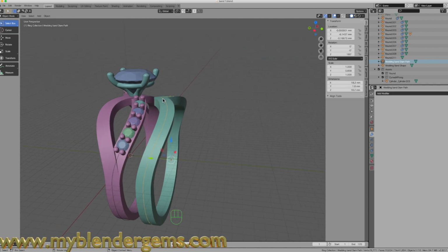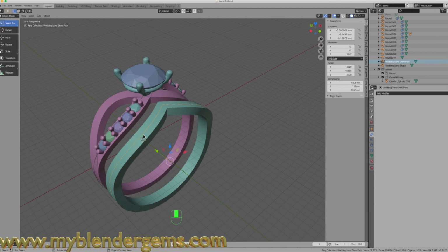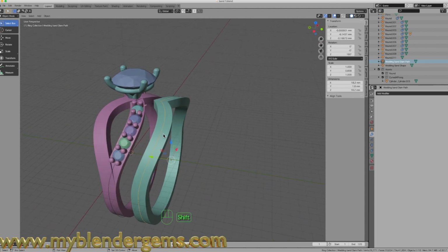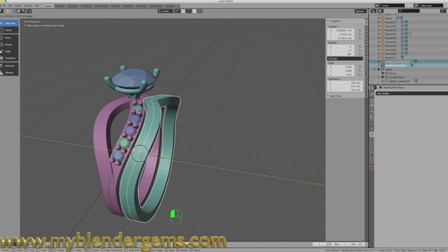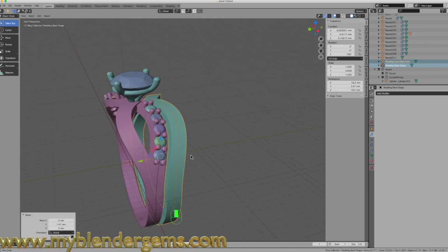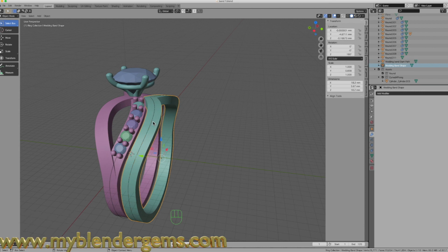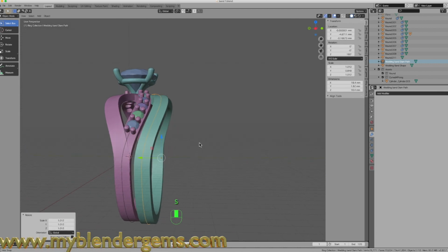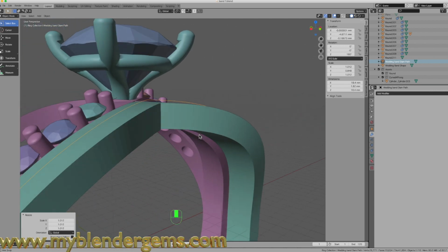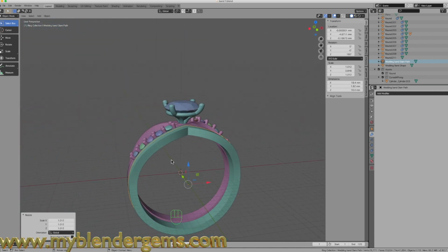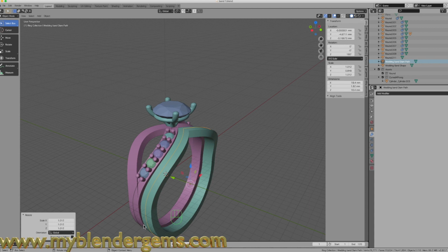and now I can start adding in the diamonds just like we did with the engagement ring. And to do this, I'm just going to select and hold the Shift key down, select the ring. I'm just going to move this over just a little bit so that we're kind of geared right up against the engagement ring. I'm going to select that path again just to make sure I can select it. I'm going to size this up just a shade, so S, and then size it up just a little bit so it's sitting above the ring, like so.